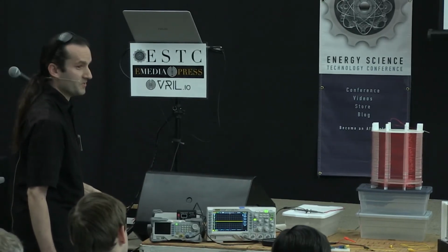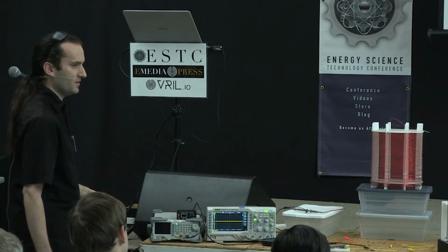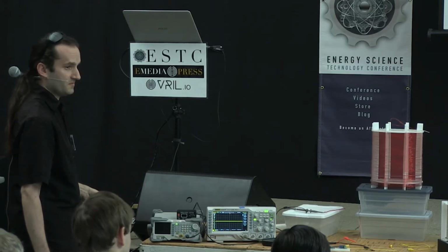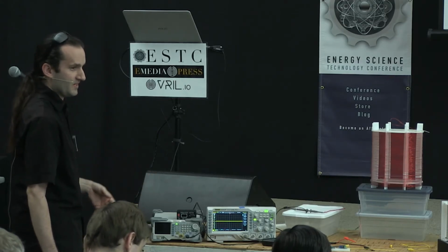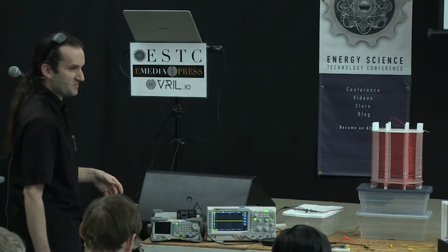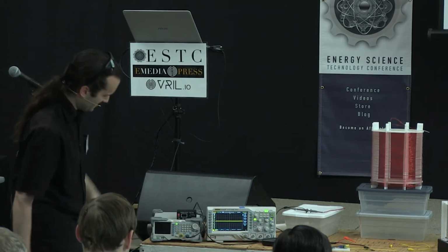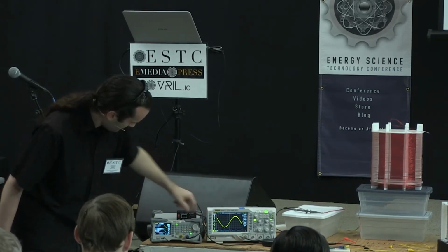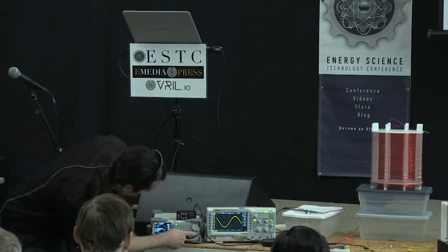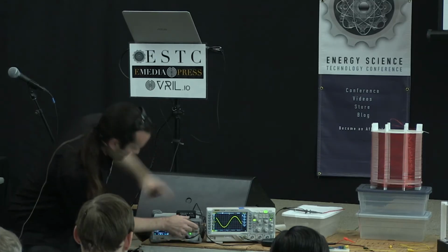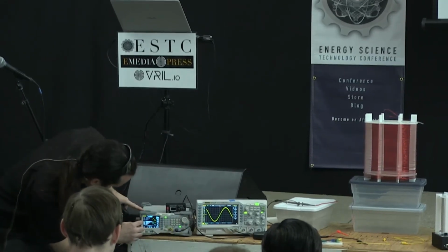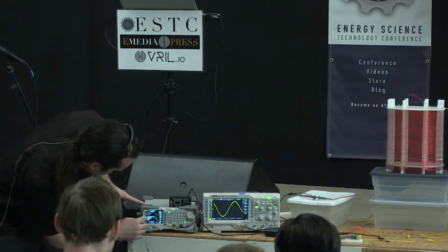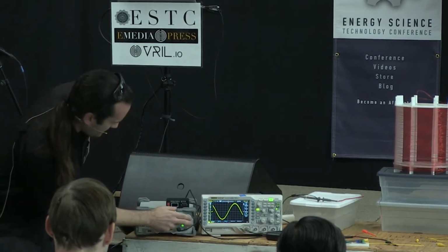A Tesla coil in the ham radio sense is considered a quarter wave antenna if you're going with the deep math and stuff. I have to short circuit a few steps to try to get all this material done. But so we turn on the function generator, and we can see we're already pretty close. If I flip the frequency around, I'm at just over 1 megahertz, 1.006.